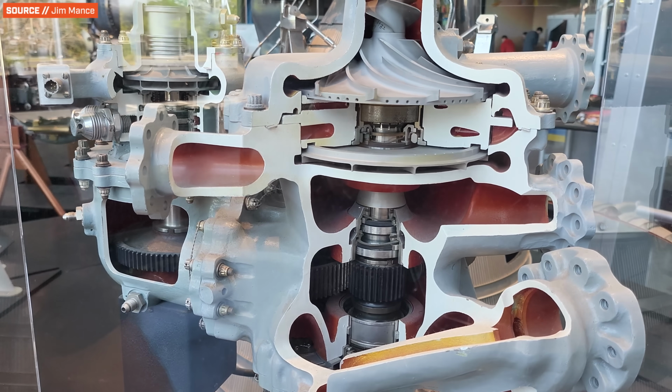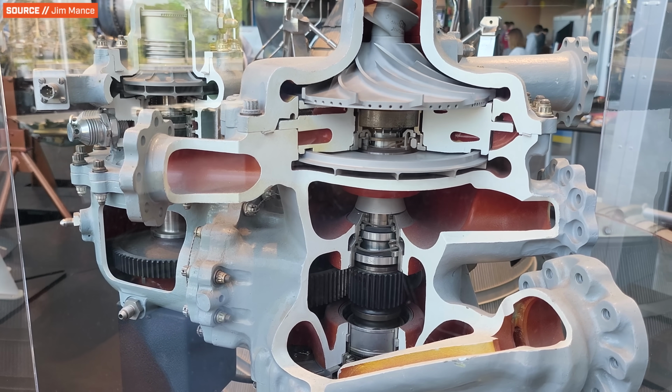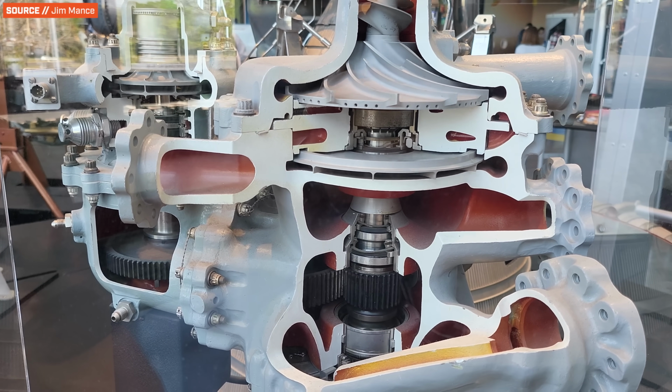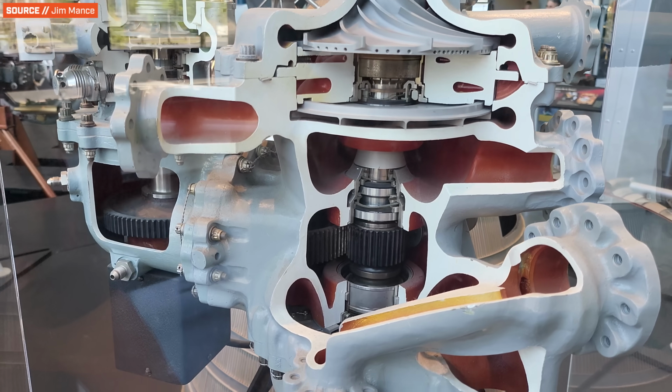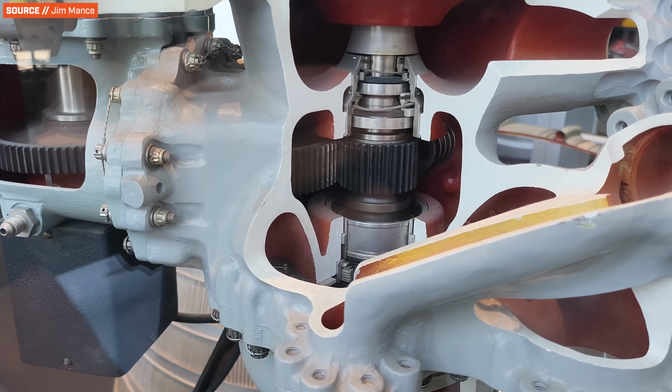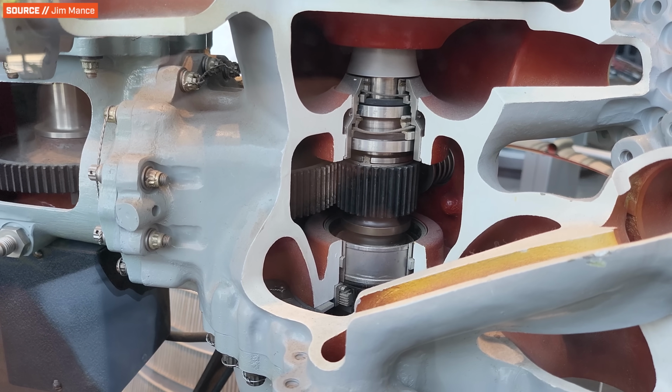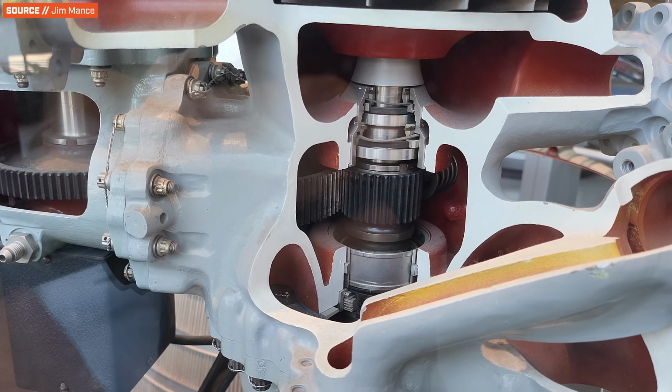In the case of a hydrogen-fueled engine with a single turbine, engineers might even need to employ a gearbox inside the turbopump so they can direct the required amount of speed and energy to the fuel pumps and send less to the oxygen pump, which doesn't require nearly as much energy. So now you've again traded one form of simplicity and efficiency for another complication and more moving parts. But it is very efficient, and it's an effective way to use what is basically free energy in the system, heat, to power your pumps.